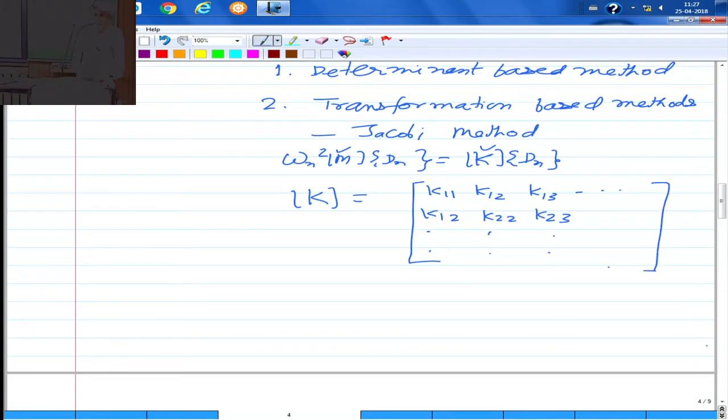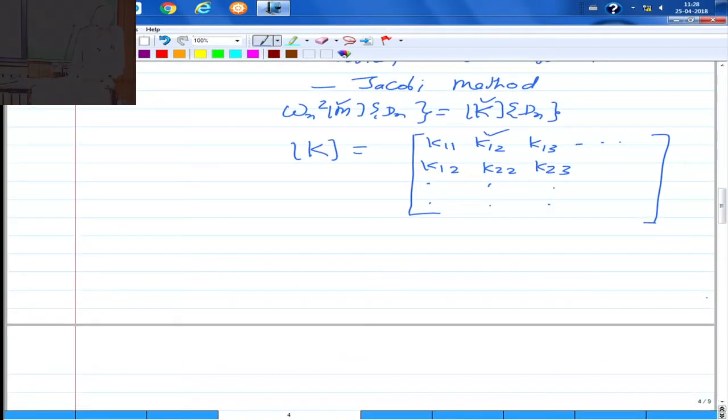So what we can sequentially do is first we construct a transformation matrix to make this K12, and similarly in the mass matrix M12, to 0. And for that we said, what should be the form of the transformation matrix and how to find out that parameter. So I had said that if you want to make K12 to 0, that is the first transformation matrix we are writing. So this T1 we choose in such a way that now one is 1, another is 2. So it's involving first row, second column, or second row, first column.